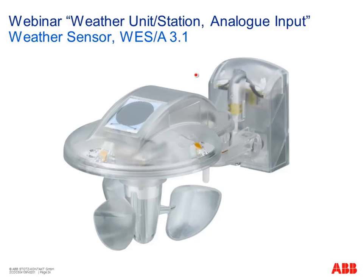Let's have a look at the weather sensor itself. Here you see a nice picture. So really different from the former version. One solution is really different: the real wind sensor we have right now with a rotating part, which is different from the former solutions, where we had only an indirect measurement via a temperature sensor. So by strong wind, the sensor was cooled down, and this was, let me say, calculated to any wind, which was okay, but not that precise, especially in the lower values.